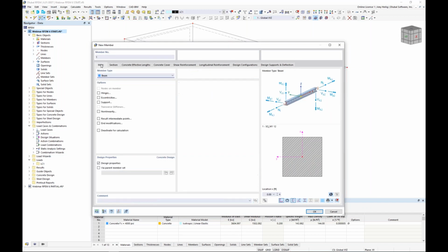Now, going back to the main tab, again, we have all of these additional tabs that are specific to the reinforcement design for the ACI standard and that concrete add-on that we have activated. I'll turn this off for now, something we'll get into a little bit later, and all of those tabs now disappear. The member is considered as fully fixed when we leave everything as default here.